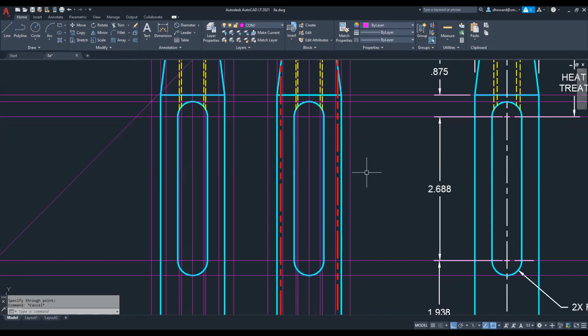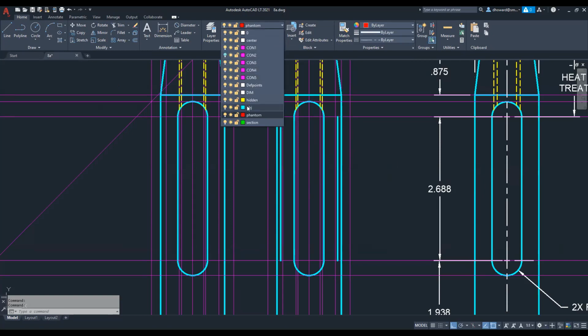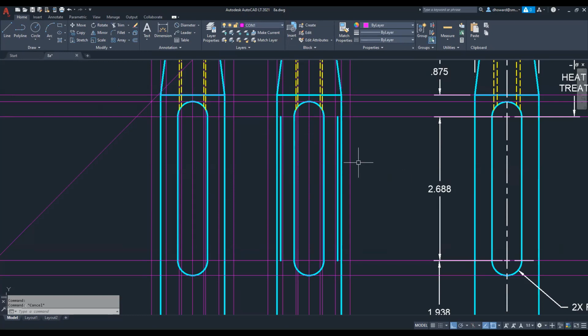And I'm going to trim that phantom line to it right now, just to show you what I'm talking about on both sides. And then I'm going to delete the phantom line, the parts of it that aren't staying. So that phantom line is truly the new edge, okay? And I'm now going to turn it into object line because it is the new edge. And these object lines on the sides, those are getting deleted. In fact, I can trim them away right now. Bye-bye.